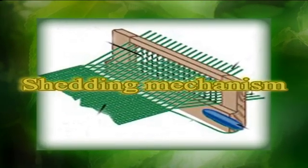Coming to the shedding mechanism, separation of warp threads into 2 parts, that is upper and lower layers, for the easy movement of the shuttle to lace a weft yarn in between the warp threads is called shedding.